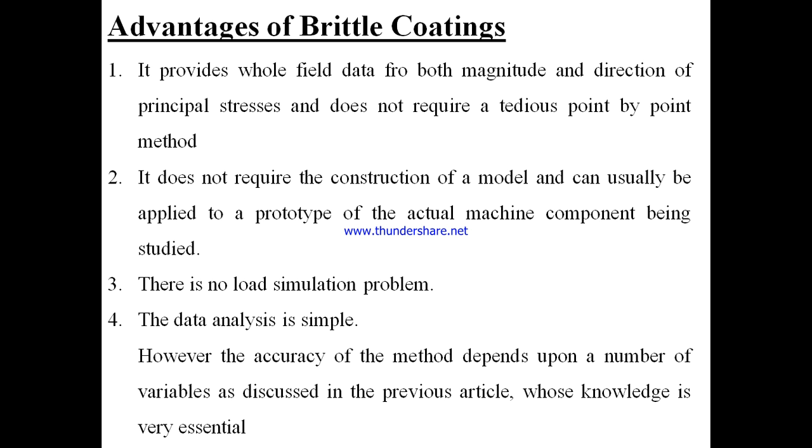We'll see the advantages of brittle coating. This brittle coating provides whole field data for both magnitude and direction of principal stresses and does not require a point-by-point measurement. And this brittle coating does not require the construction of an actual model and can be used actually on a prototype of the actual machine component which is to be studied. There is no role of a simulation problem here. The data analysis is very simple, as you have seen. We just have to give the coating number, specify it, and see the crack patterns.